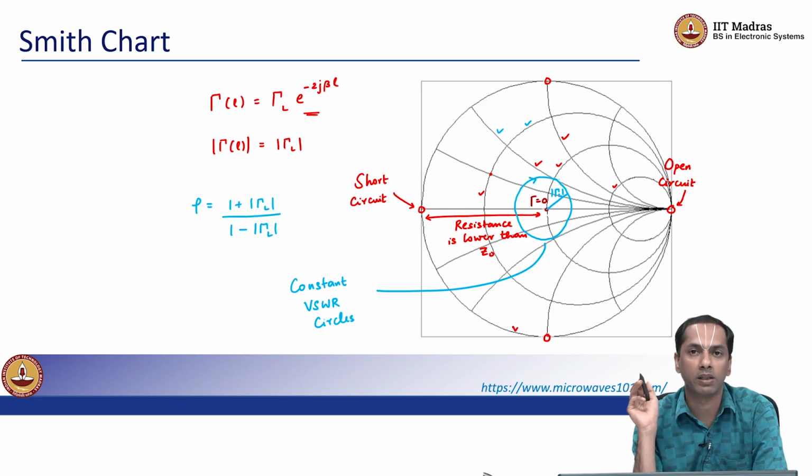So there's nothing to worry about in terms of being daunted by the looks of a Smith chart. It is but a simple transformation that helps us visualize data. Mainly, I would say the convenience is, for example, open circuits or infinite loads are something that we are able to realize very easily, right?